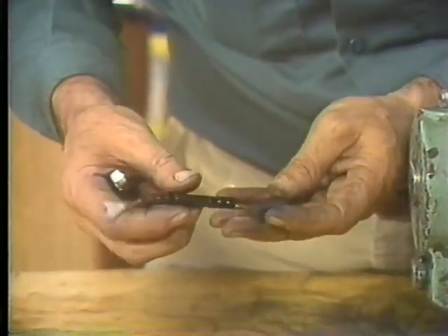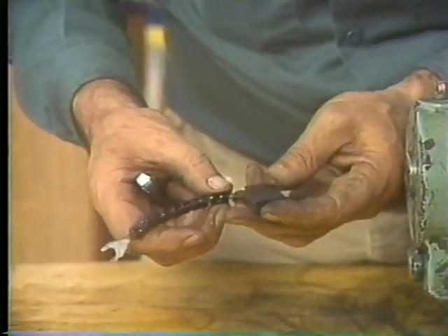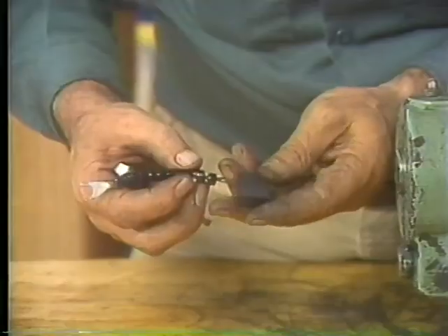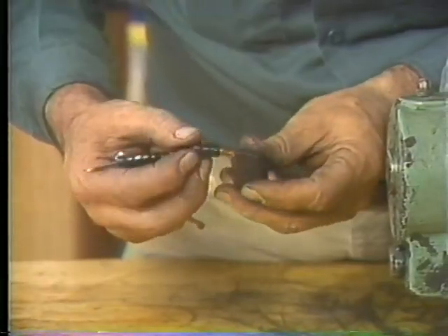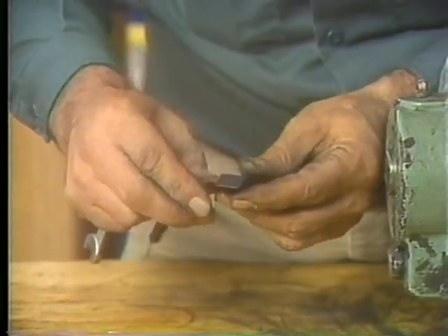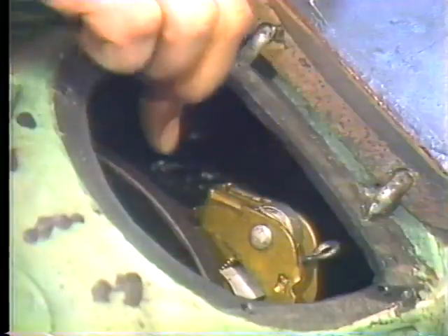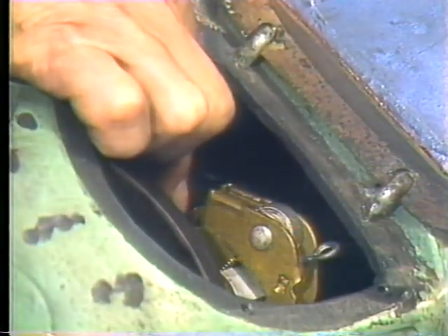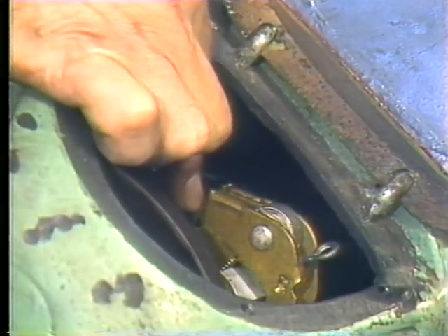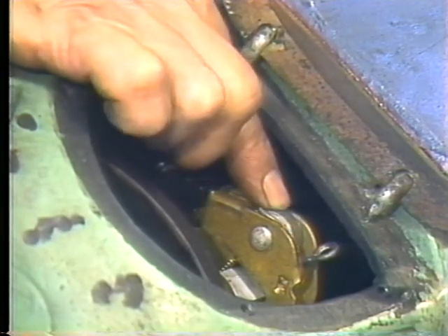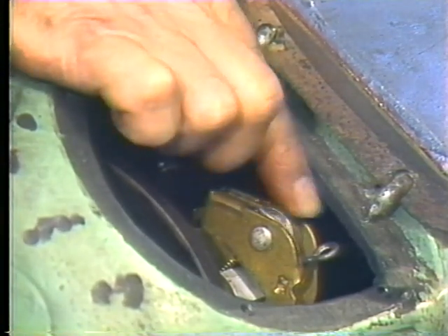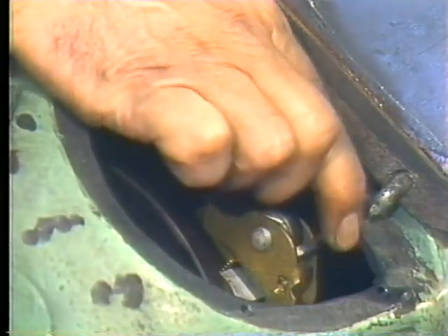All the other brushes have to pass this checklist too. If the brush doesn't meet each of the requirements, replace it. All right, next we'll look at the brush holders. The insides should be clean and smooth. If there are burrs or dings inside, the brush might get hung up on them, and then it won't make good solid contact with the commutator. These bottom edges should be smooth, straight, and free of burns.